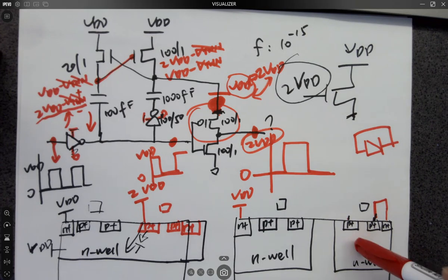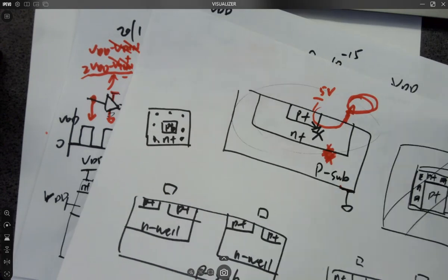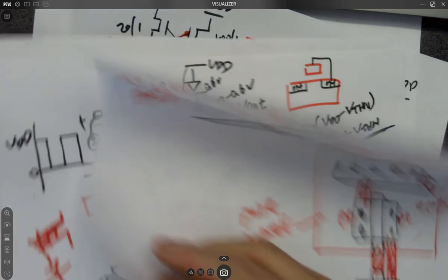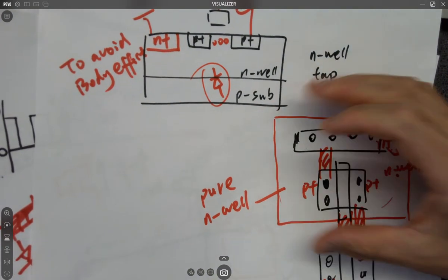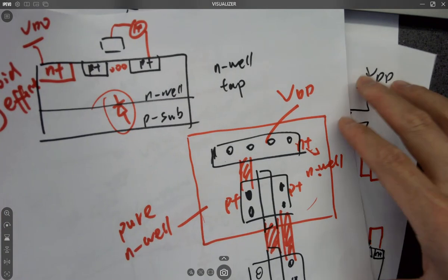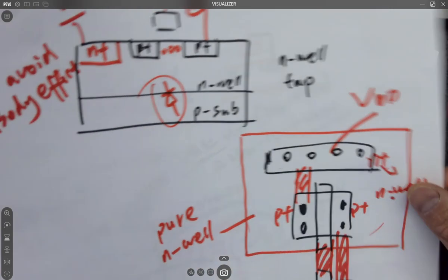And eventually, you separate it in your layout. You can definitely do it manually, right? You know how to do that. In your N-well, just don't have that shaded area overlap. Just separate them. The dotted areas of the PMOSes, just don't let them contact. When you are drawing these, you eventually draw a universal N-well to cover both the N-taps and PMOSes, but now you just don't do it. You have another PMOS next to it, have them separated, so you don't have the universal N-well covering both.